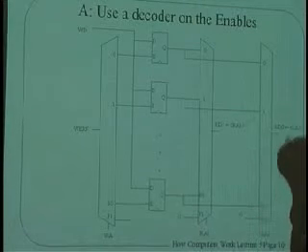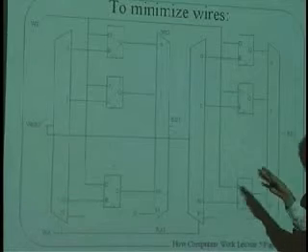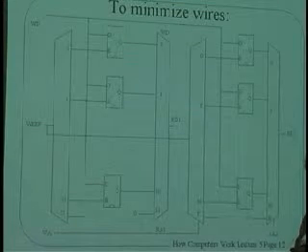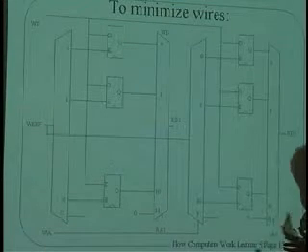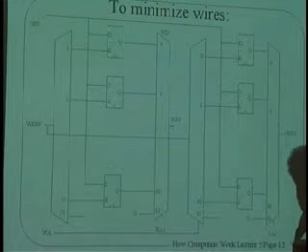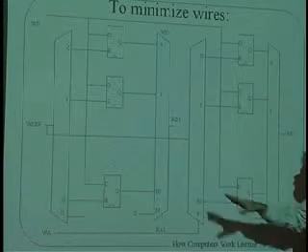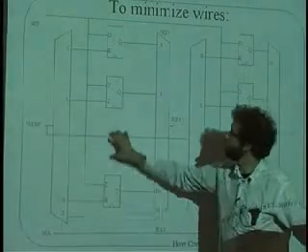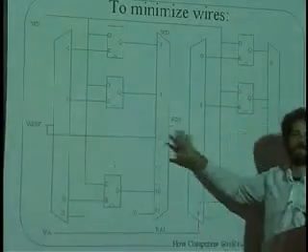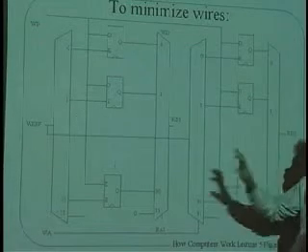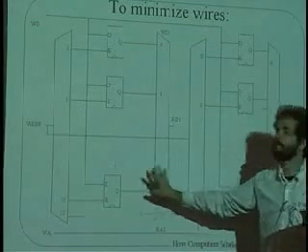So a neat little trick, which I want to show you and I think you'll like, which they came up with in those days, and it doesn't matter quite so much now that integrated circuits are so much more dense, is the following trade-off. And this is indicative of all kinds of trade-offs that you can make between complexity and cost. Instead of having the same bits from all of these registers go to two multiplexers, what architects in those days did is that they duplicated the register file twice.